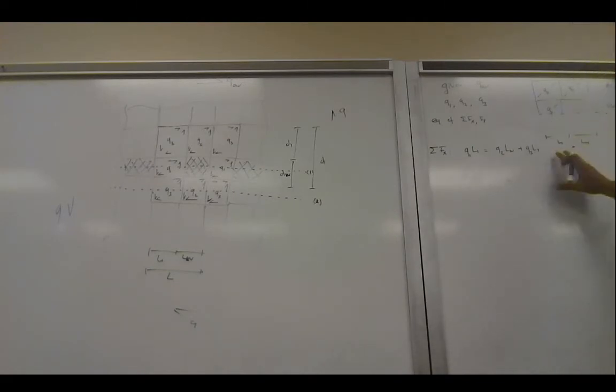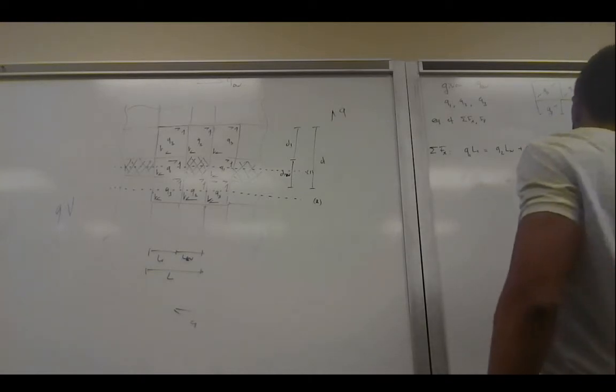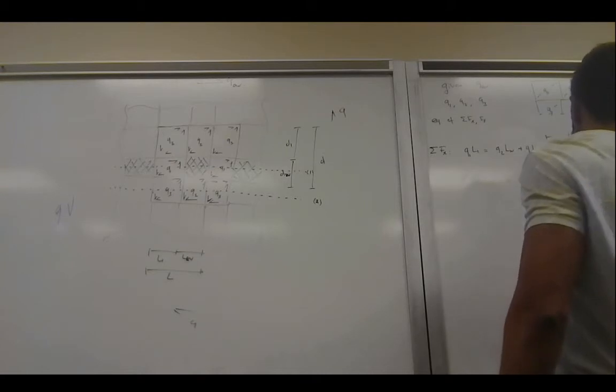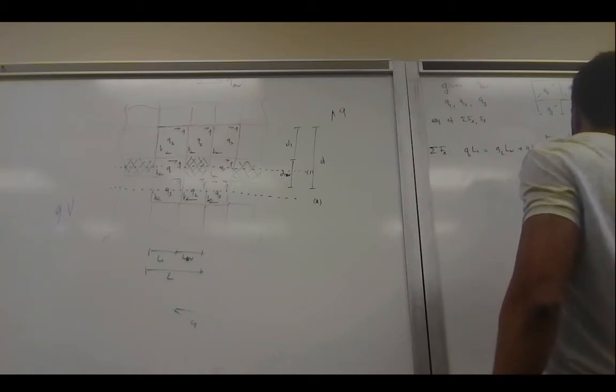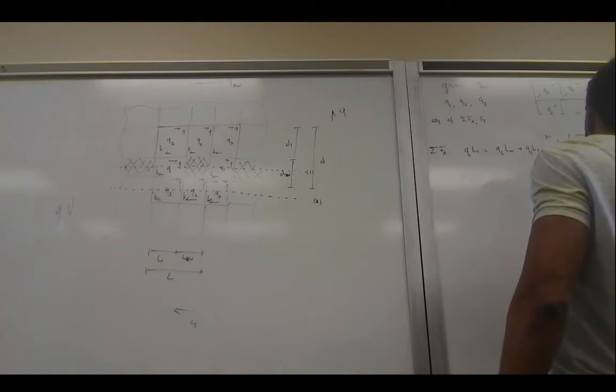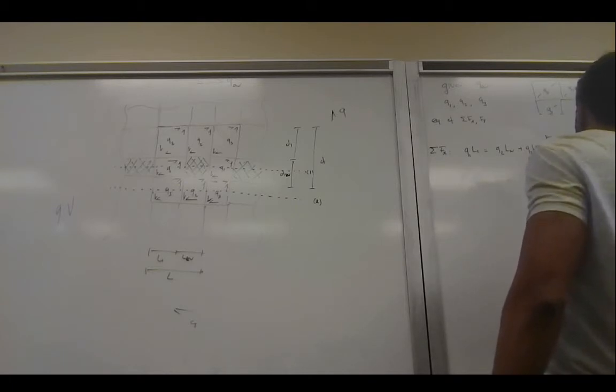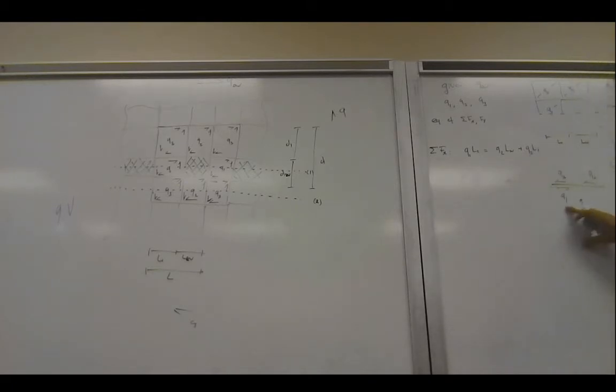So basically, if you would make a free body diagram out of this, what you will get is, say, panel 1, so this is Q3 acting in the X direction, this is Q2 acting in the X direction, and on this segment, Q1 is acting. Okay. Does everybody get this step? So that's just the line that runs from Q2. Yeah. Okay, so basically just at this location. Got it.